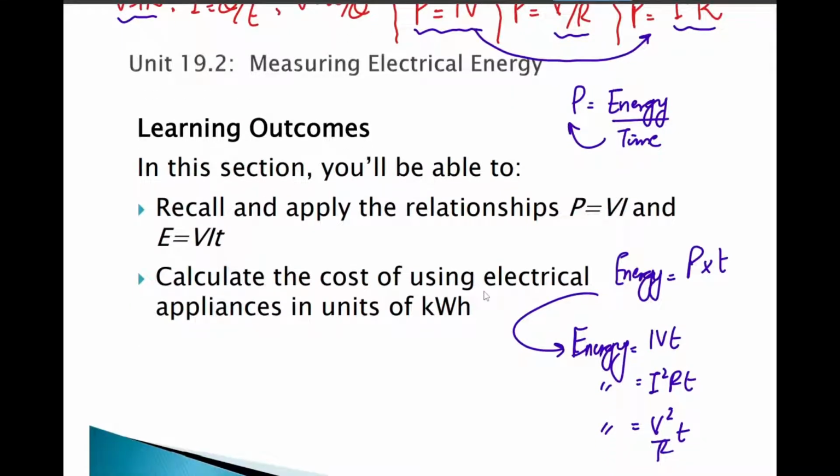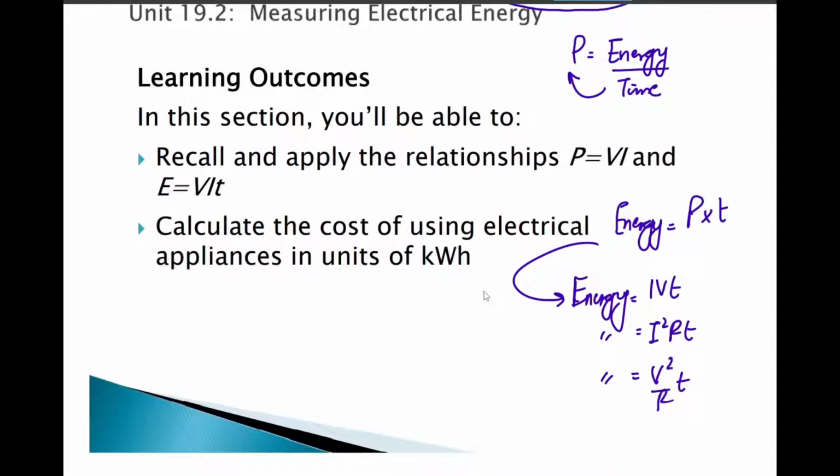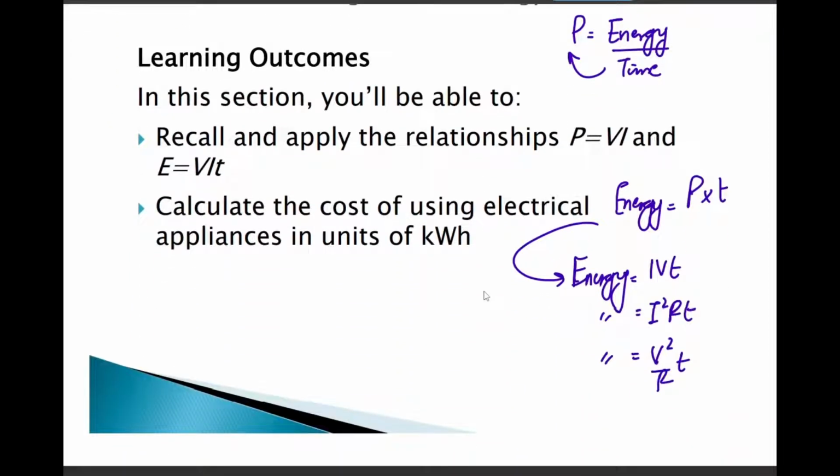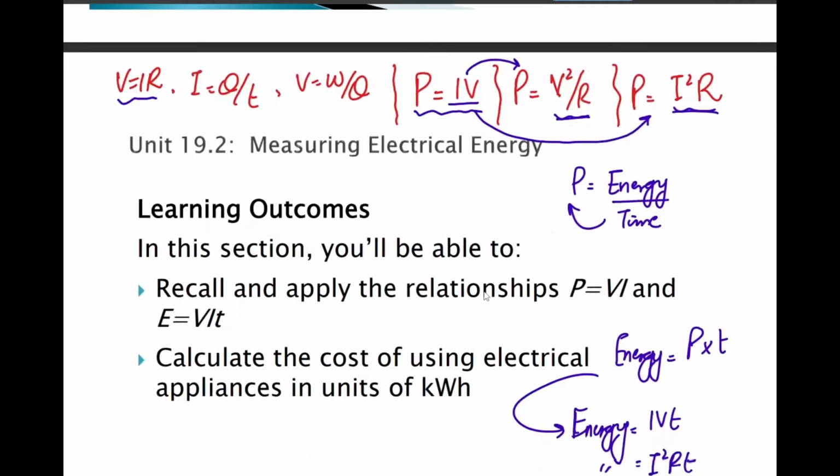And all of them are for the energy, and these are for the power, right? And these last three that you've written are the rearrangements of the original one for electrical power. Exactly. So I'm putting in first IV, then V square over R, and then I square R. And the current is the electrical current that we studied at the very beginning of the chapter. When the current flows through the circuit, it has some voltage as well, that is the energy of the electron. Current is the flow of charges, how many electrons. Voltage is the energy of the electron. The concept remains the same throughout the chapter.